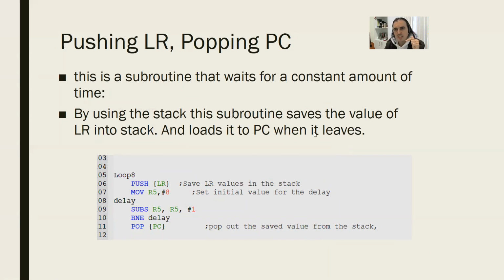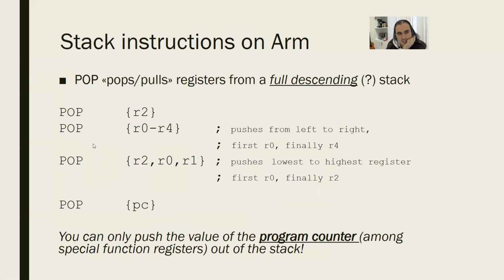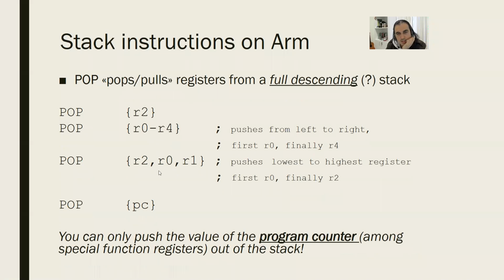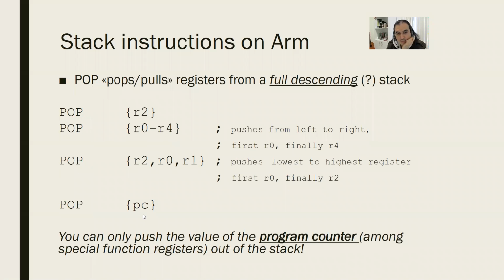In the definition of stack and push and pop, I've omitted these lines. I've shown you how to push registers and how to pop registers, of course, push and pop. And there's also a definition here. And for push, it is only LR. And for pop, it's only PC.